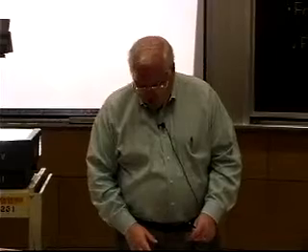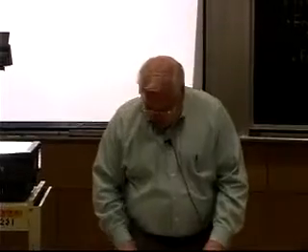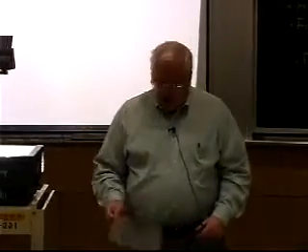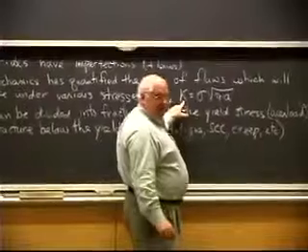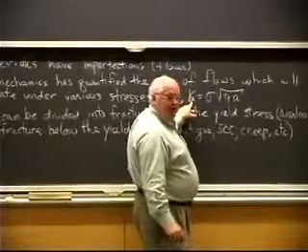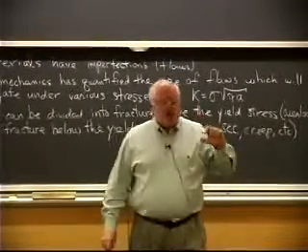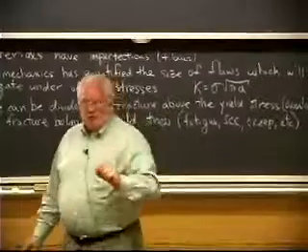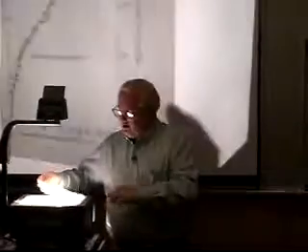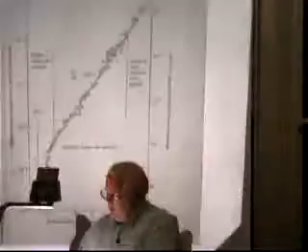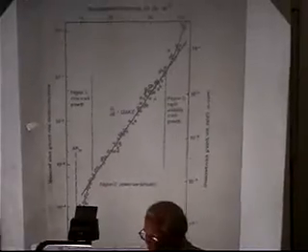But if I go to fracture, people started thinking about this and said, well, if I start applying fracture mechanics, instead of doing stress versus number of cycles, I ought to be doing stress intensity, because that's the more important thing. It's the flaw, it's the stress intensity at the tip of the crack that's going to be driving the crack, not the global stress.